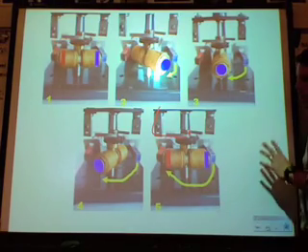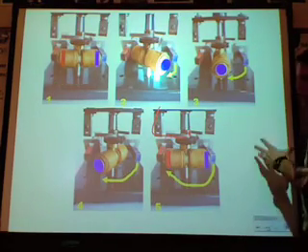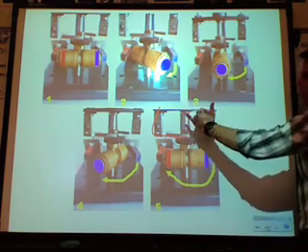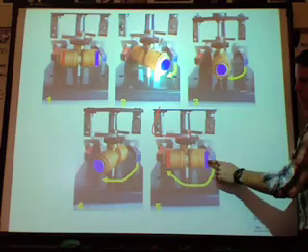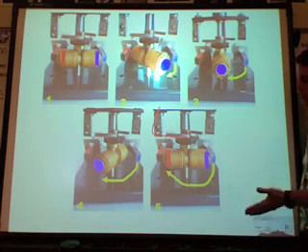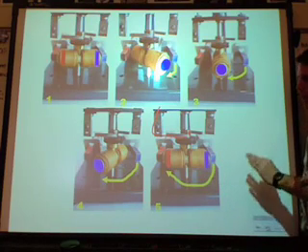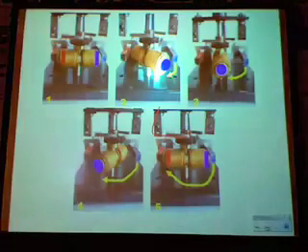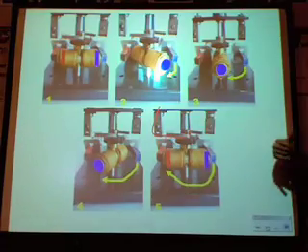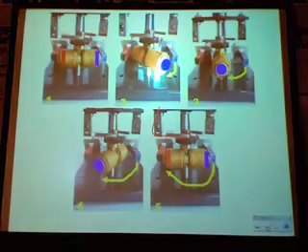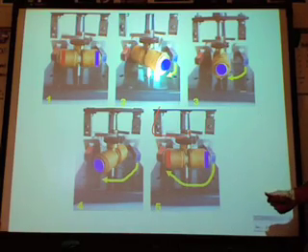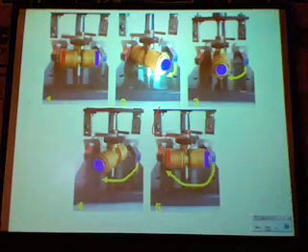So once again, in order to keep that motion going in a real normal motor, we're going to want to switch the poles. We're going to want to change the connections to change whether we're being repelled or attracted. And we have to do it at the right point in time. And the motor you're going to build in a couple of days, it's going to keep going because gravity will make it go back, and your switch will allow it to be turned on at the right time. It's like pushing a child on a swing.